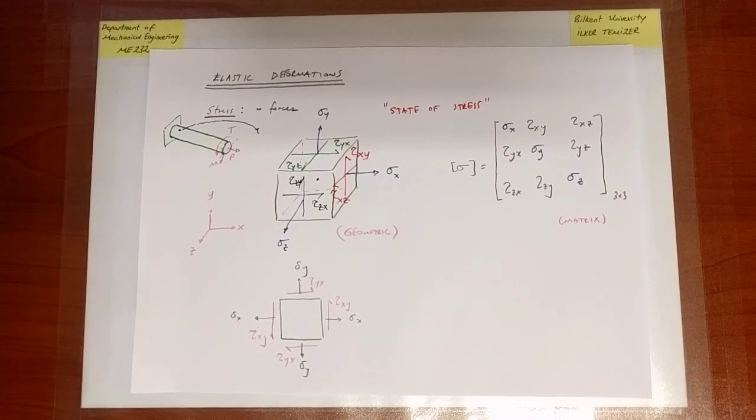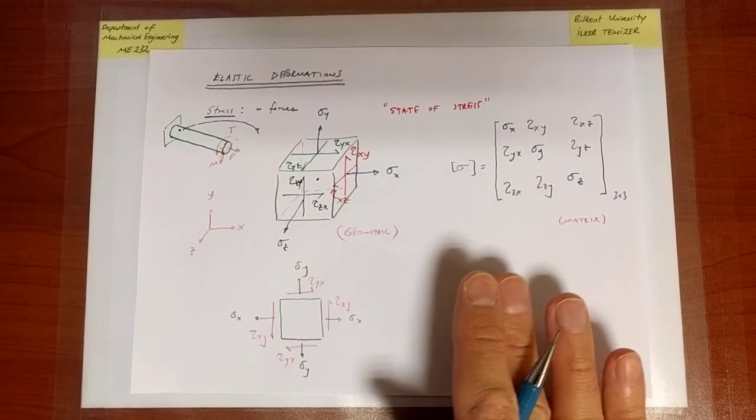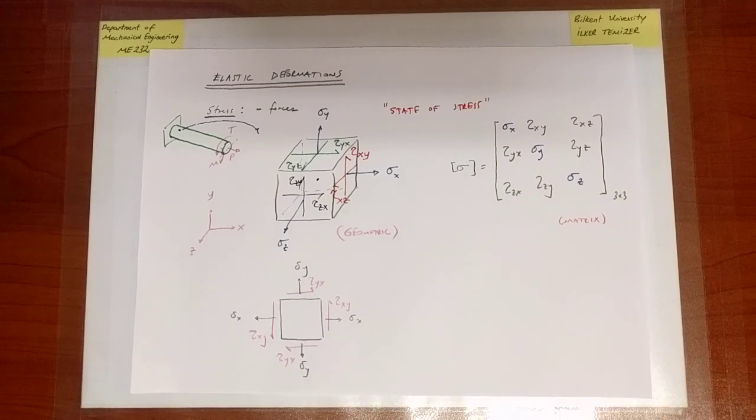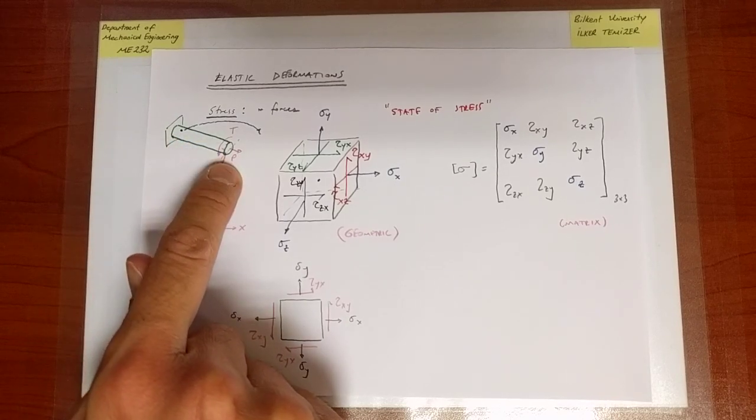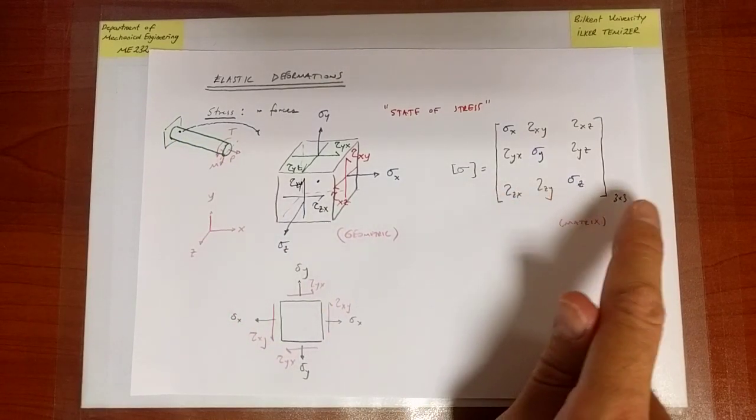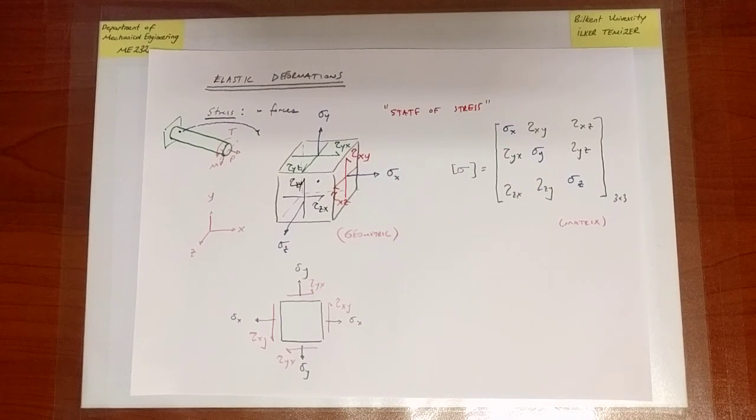Okay. So now when I look at the representation of the stress in matrix form, in a mathematical form, if you like, I see 9 components. And now our next question is, does the stress have really 9 components? In other words, if I want to know the full state of stress at a point in a loaded structure, do you need to provide me with all the 9 components? Or is it sufficient perhaps that you provide less?